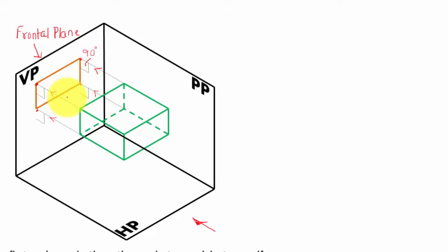So we have this front view, and let's see how the top view can be obtained, and for that we're going to look at this object from the top. Something like this will happen. Let me show you. Again, these are the points at which it has been struck, and you can clearly see when these points are joined in proper sequence, we have a view. Alright guys, something like this, and obviously these projectors are gonna be making 90-degree angles.